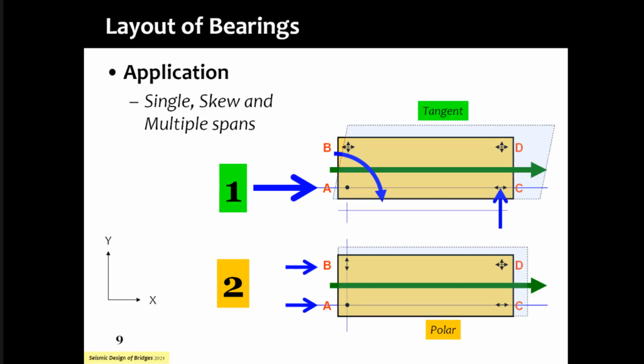And that is why we want you to recognize 3 types of bearings: restrained, guided, and free bearings in the horizontal direction. In the vertical direction, we pray that we are not having uplift, because most bearings that we get do not have the capacity to carry uplift in tension, but they can carry a lot of vertical load, many of them.